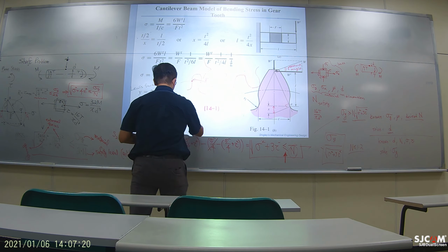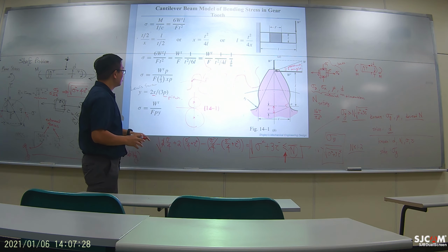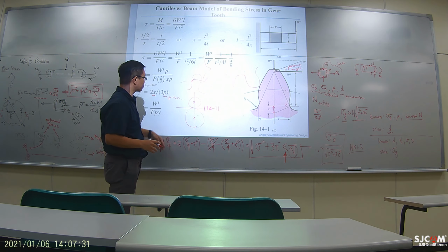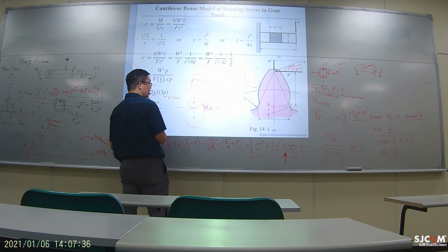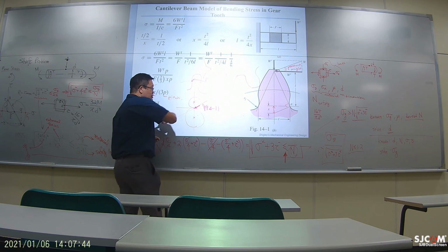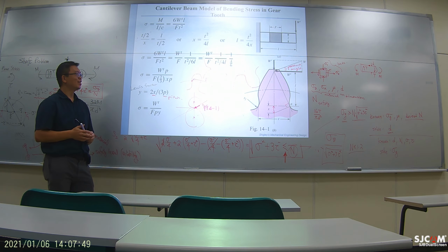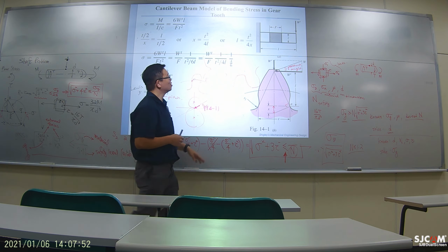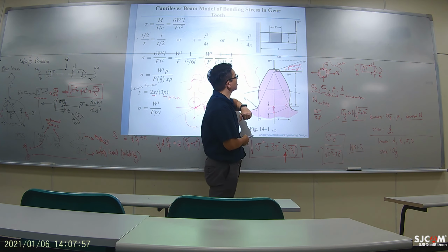Okay, so if you have two pitch circles between two gears, there is always a pressure angle. So the force coming from the other side passes through this particular straight line having a tilt angle. And this is how this model knows where the force comes from.